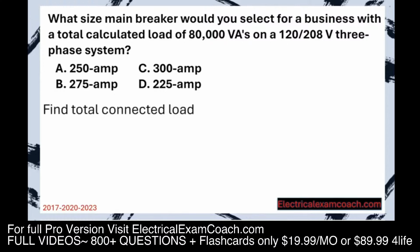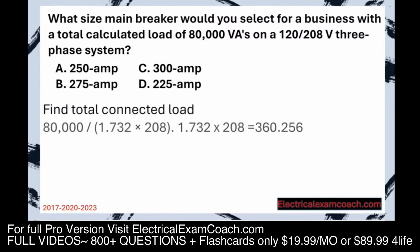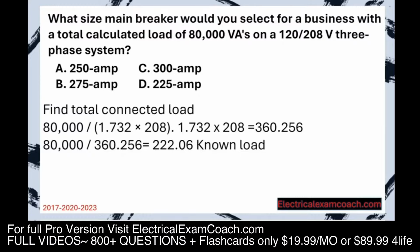Step 1, find our total connected load. In this case, they've done the work for us. They've given us the 80,000. Now all we have to do is divide. We do our little bit of pre-work and we end up with 360. Now we divide that out and we end up with 222 amps.